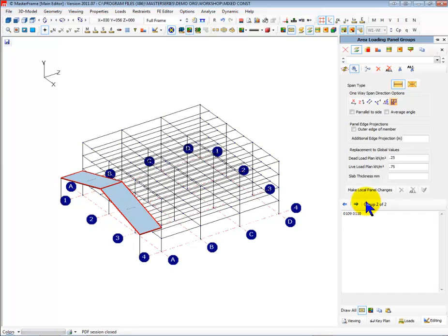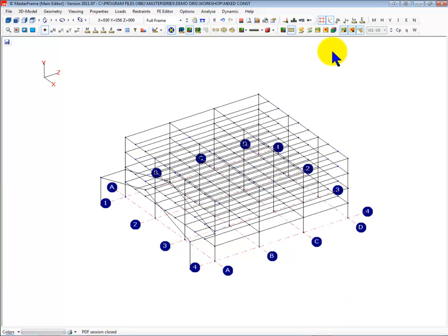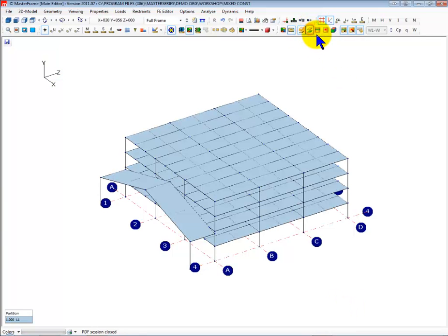So, and I've put nothing in here for the thickness. So what will happen? Very good question. If I look at my overall area loading with my key plan, so I get rid of this, I don't need that for the time being. At the minute we're saying partitions of 1 on both surfaces. Even though this is steel, it's still thinking the partitions exist.